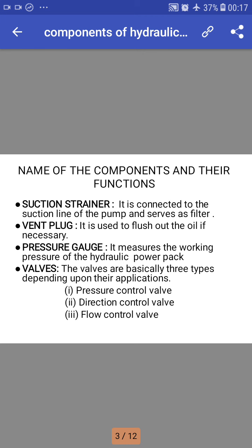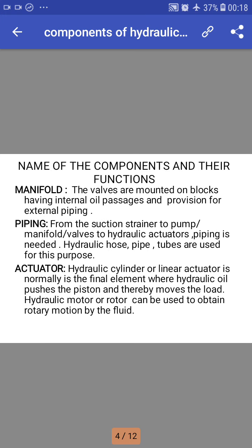The direction control valve. The main function of the direction control valve is to direct the fluid flow. For forward motion and reverse motion, we can use the direction control valve to control the flow. And the flow control valve: to control the flow velocity, the flow control valve is used.